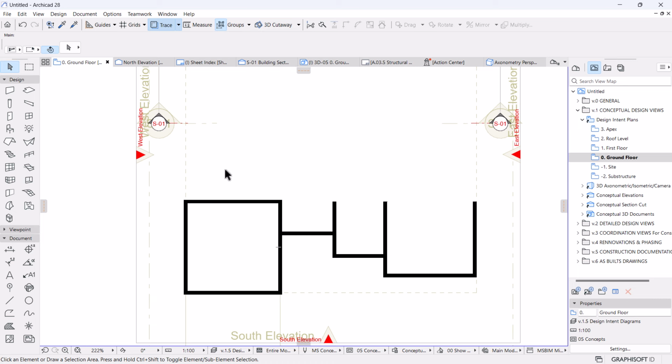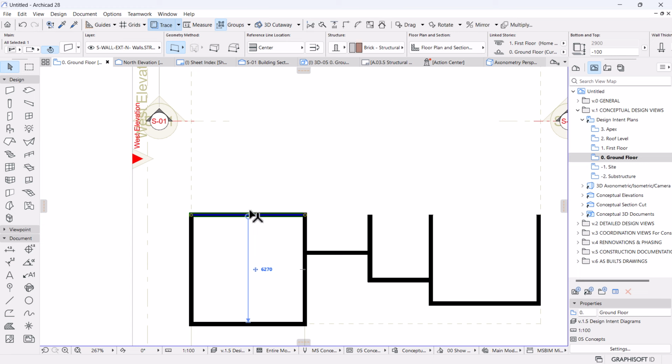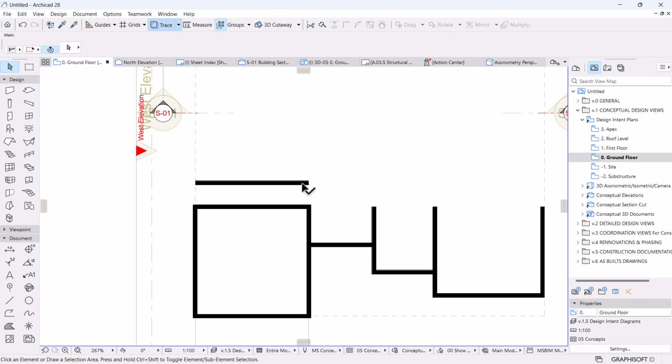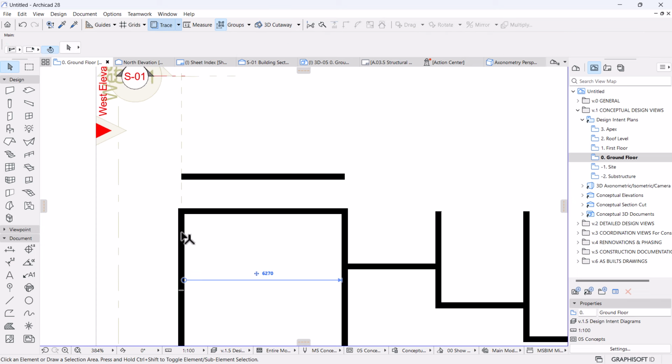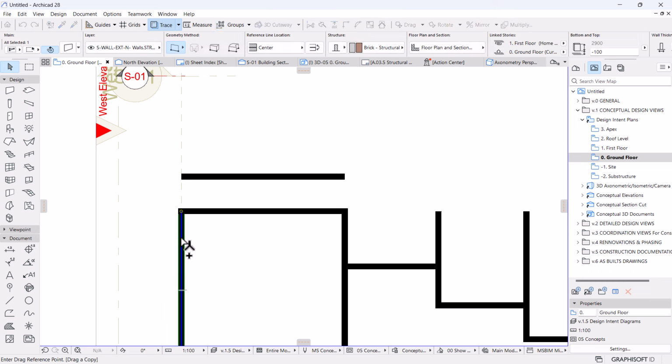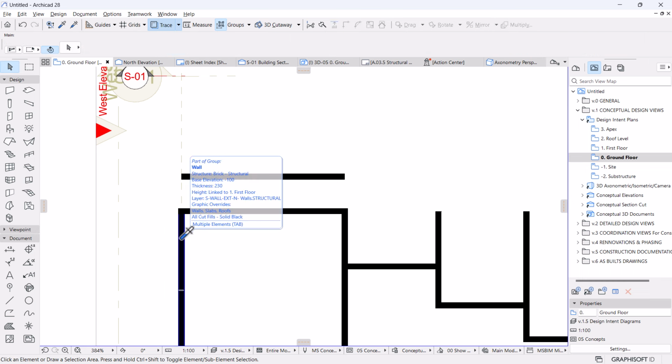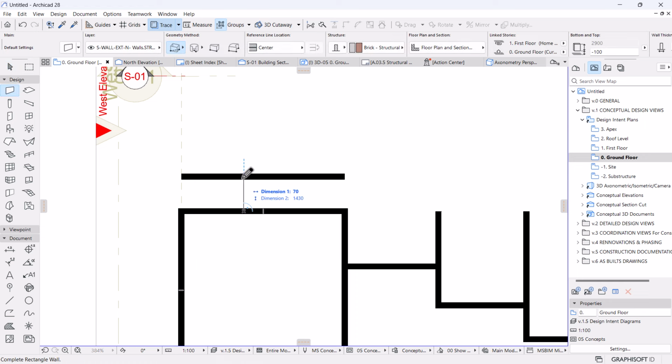Okay, from here let's move further up and create other spaces. So we have the garage. Next to the garage here is going to be a powder room, so I'm going to Control Shift D and copy this up by, it's going to be a powder room of the width of, let's say, 1.5 for now. This should be 1.2 exactly. Perfect. Then the powder room, obviously I need to close it off at the back. Let me change this line type to a single, and then there.